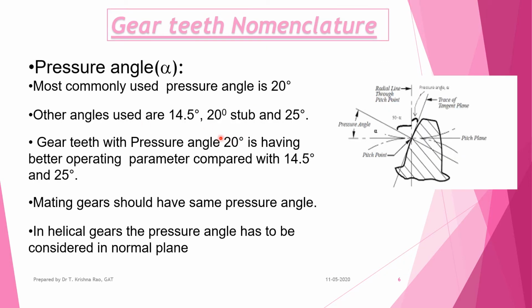There are three standard pressure angles recommended in the market: 14.5 degrees, 20 degree full depth involute, 20 degree stub, and 25 degrees. These are the pressure angles recommended, and Indian Standard recommends only 20 degree full depth involute.